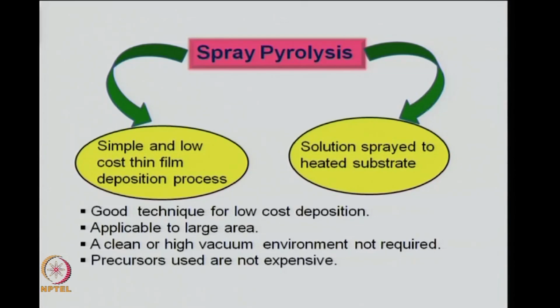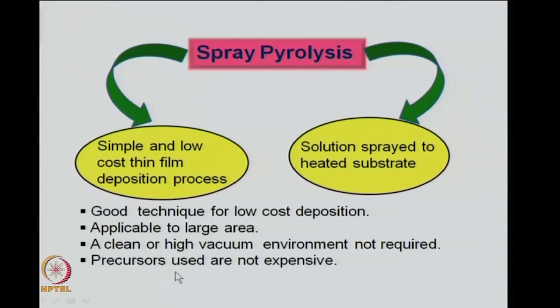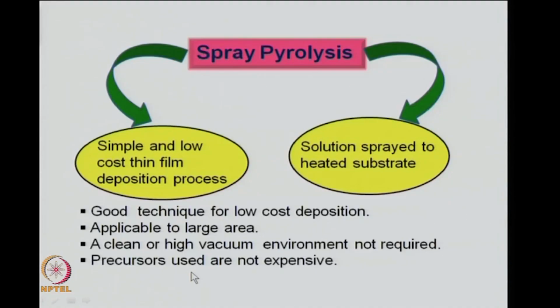For example, you do not need extremely clean rooms or clean environments like those used for certain very sophisticated techniques. You do not need a high vacuum to do this kind of spray pyrolysis based thin film deposition. The precursors, that is the starting materials that you use, are not very expensive.